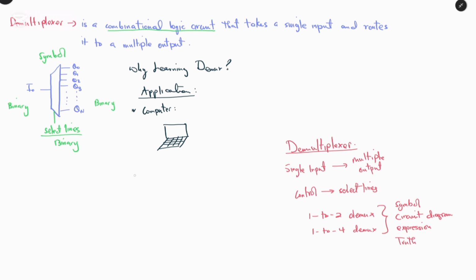In the other case where we have a multiplexer circuit, and the signal from the multiplexer circuit we want to have a DEMUX, this single input can be passed to various outputs, Q0 to Qn. From those multiple inputs, I0 to In, we can pass through a single channel.